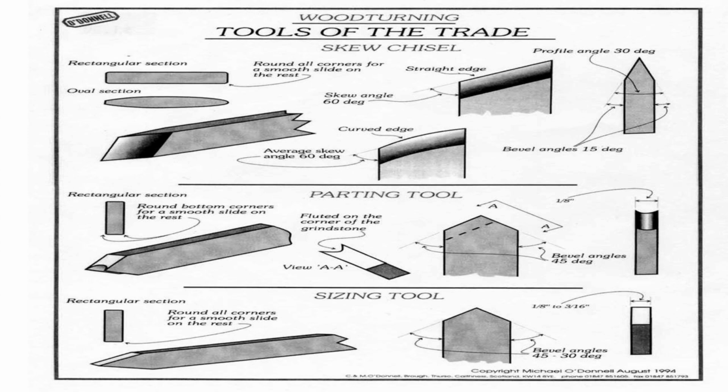The other thing on a skew is that if you look at the side grind of the angle, that generally is about 1.5 times the thickness of the skew as you go through. And again, what works well for you is what you should use. Look for a flat face on your grind, or a concave face. This is a hollow grind, so it's concave. And the nice thing about the concave is that as you use a skew, you can very quickly go back with a hone and get a nice sharp edge on it in between sharpenings. If you hone a concave ground skew, you only touch the tip and the heel, so it's very easy to hone an edge back on it rather than take it back to your grinder.